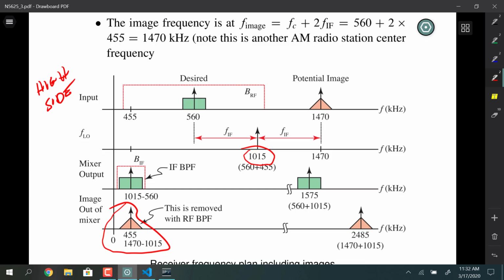But if we put the bandpass filter at the front of our converter, frequency translator, as shown here, nominally, it's not going to be a brick wall like that, but have adequate attenuation so that it doesn't let any of the image frequency get in.